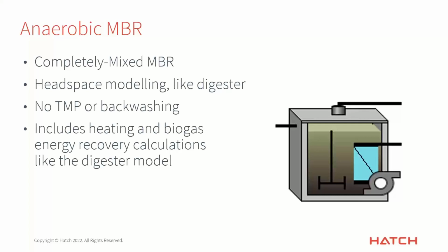So it's a completely mixed MBR. You'll notice it does not have any bubbles in it because, of course, it's not aerated. So it's anaerobic only, with headspace modeling just like a digester. That's why you see that there's a lid on it here and that we have our gas connection point like we do for the digester. The TMP and backwashing is not present in this model. We don't have that other extra set of calculations in here.